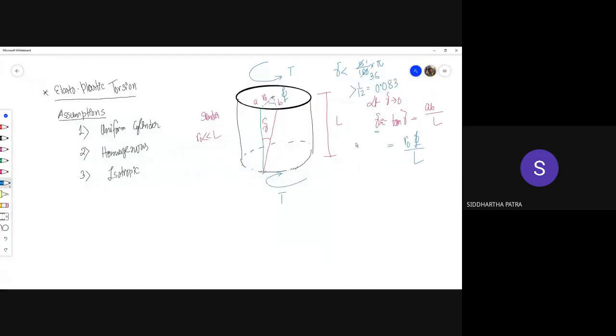So the strain, you need to understand that if I talk about gamma in terms of angle, this is small enough angle to have gamma equals tan gamma. But as we have discussed so many times, the elastic limit of strain is around 10 to the power minus 3, and 8% strain is definitely well in the limits of plasticity.